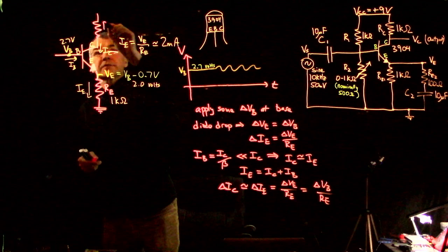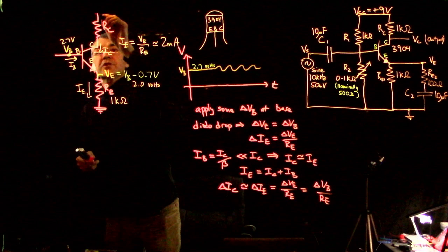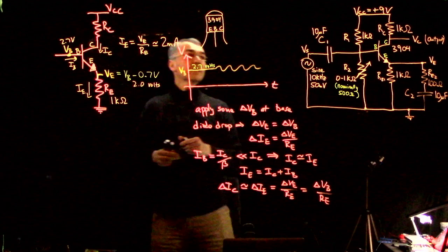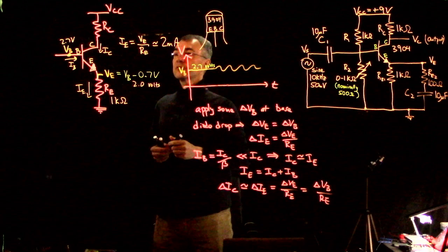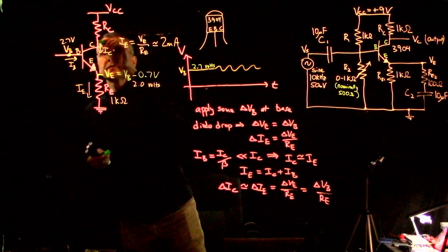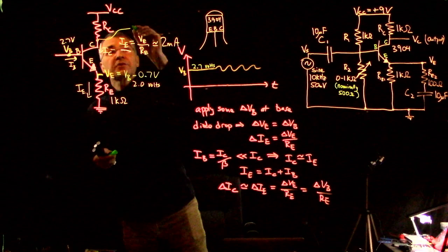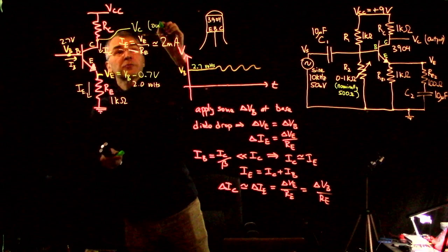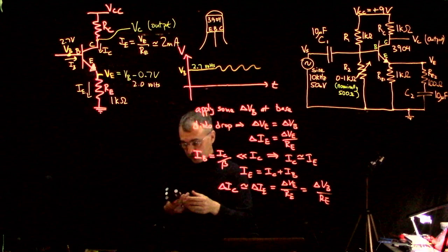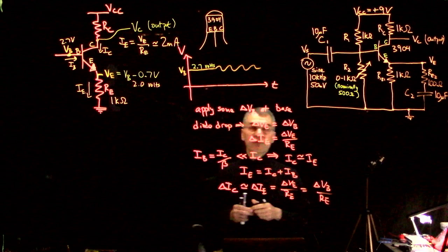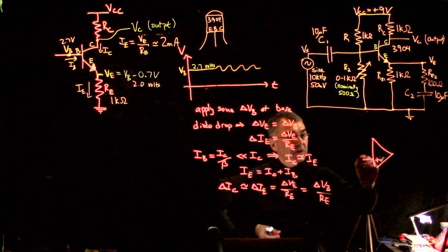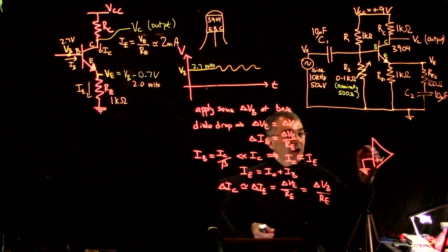So here is the collector resistor, and then we call this VCC, which in our Electronics Explorer board has tended to be 9 volts. Okay, and then the output of this circuit is over here. So this collector voltage is our output. And again, remember, our goal is to make a circuit that behaves in an analogous way to the inverting amplifier that we're accustomed to from op-amp world.